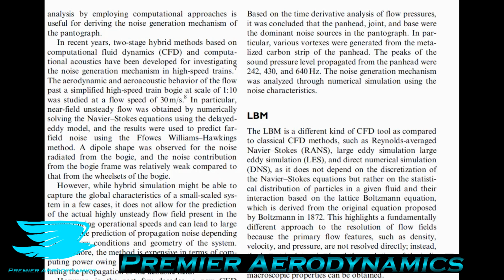For URANS, for example, there is so much simplification, and the boundary layer equations that you use are so empirical and heavily simplified that the information that you need to predict noise and to model noise is not completely lost, but very obfuscated. Like it's very little information left. So trying to get accurate noise generation and propagation from these CFD methods is challenging at the best of times.